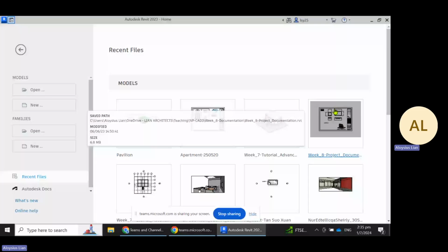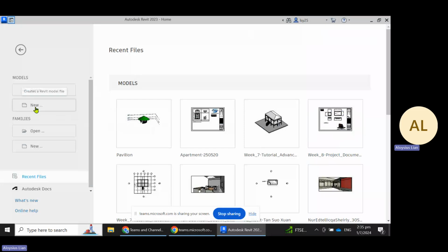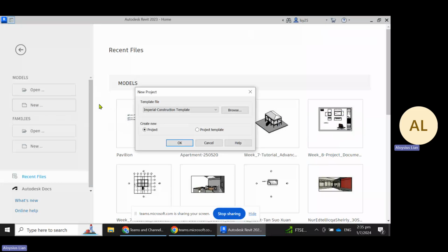Hi, so today's tutorial is to show you how to use Rhino Inside Revit and use the built-in categories to add element types within your Revit file, as well as also display within the Rhino interface. So just head into New and Metric Architectural Template, click OK.